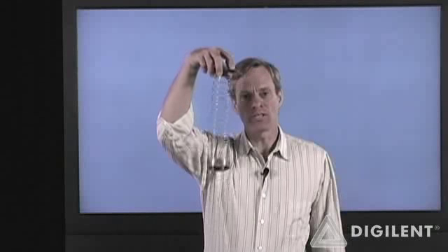We can also consider our Slinky to potentially be a time-varying system. If I'm operating this Slinky, bouncing it around, and I decide to change, for example, the temperature on a regular schedule, the physical parameters of this Slinky, like the Young's modulus, which contributes to the spring rate of the Slinky, may change as I change the temperature. I'd have to change the temperature quite a lot, granted, but I could make them change. If the temperature is changing as a function of time, it may look like the Slinky's parameters are changing as a function of time. The resulting governing equations would now be differential equations with time-varying coefficients.